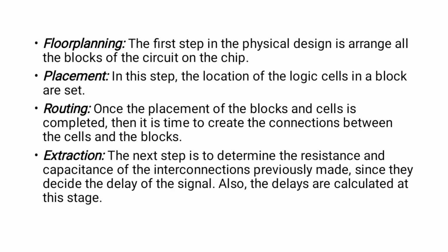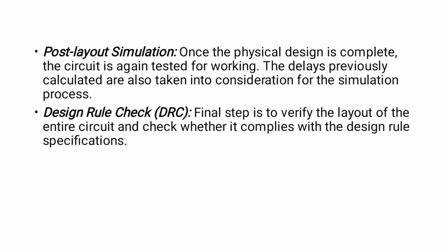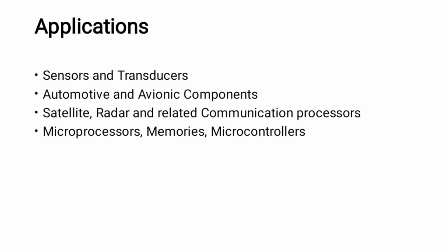Extraction determines the resistance and capacitance of the interconnections previously made. Since they decide the delay of the signal, all delays are calculated at this stage. In post-layout simulation, once the physical design is complete, the circuit is again tested for working, taking the delays into consideration. The final step is to verify the layout, and then we go for the fabrication process.